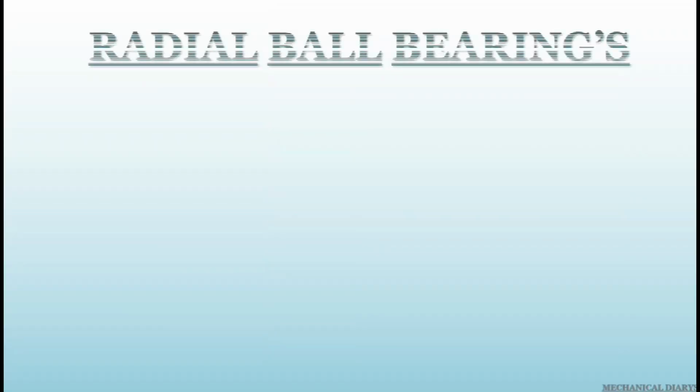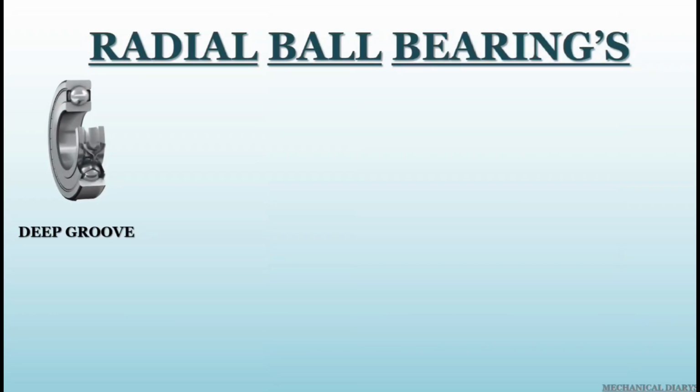First we'll see the details of radial ball bearings. There are 4 types of radial ball bearing available. First is the deep groove ball bearing. This bearing type has low friction and can operate over a wide range of speeds and can carry radial and axial loads in both directions.